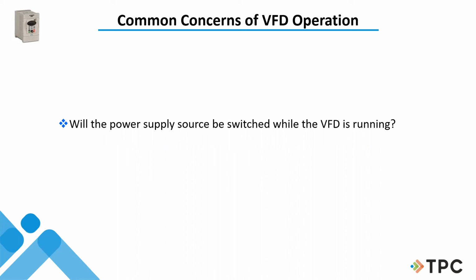Here it says, will my source be switched while the VFD is running? There are some places that do that. A lot of people put emergency contactors in front of some of their drives. So it just depends on the process or your system. But if it's going to be switched, you have to know it, because a lot of the drives fault out when you take the power away from it because you didn't turn the drive off first. You took the power away from it. So that's just like a loss of power.